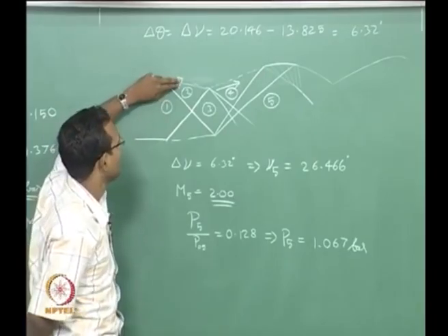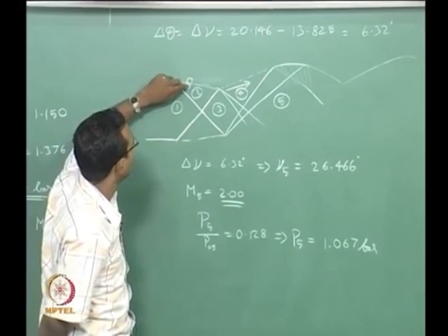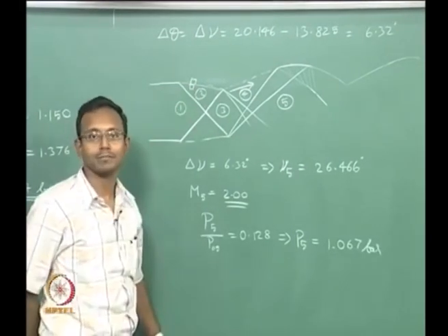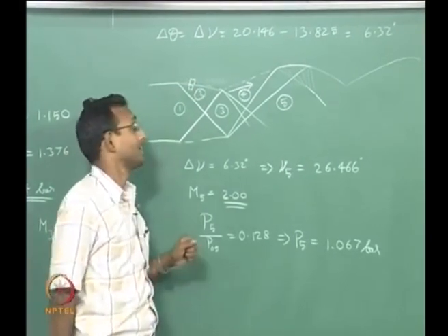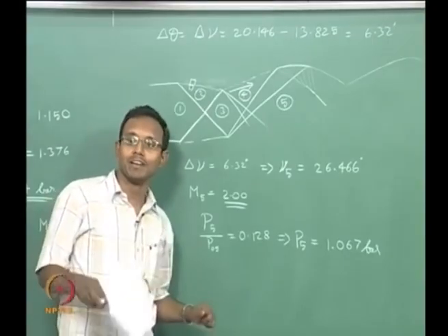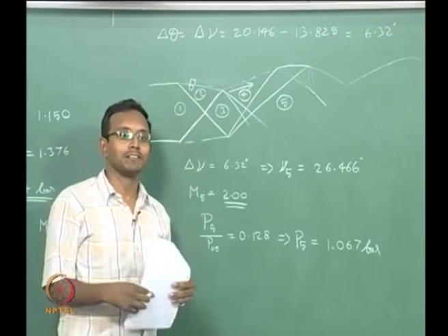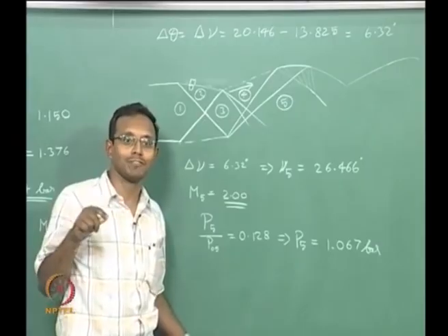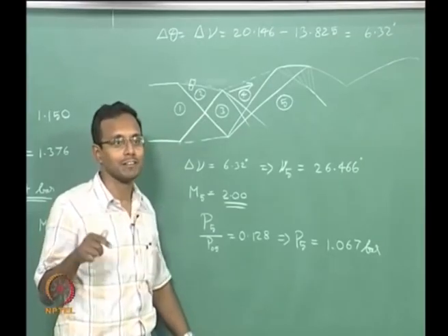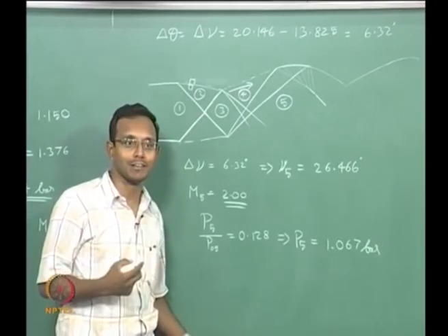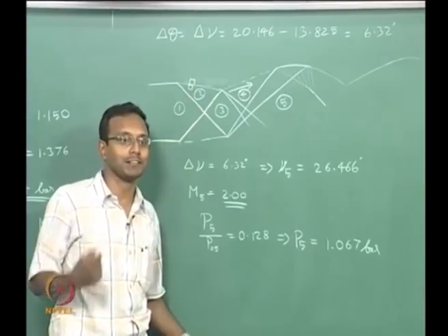If that is the case, there is going to be a very high velocity gradient at that point. If there is such a high velocity gradient, you can immediately think about vorticity being present there. Vorticity is the curl of the velocity, del cross V vector. So I can now tell that there is a non-zero vorticity present there.